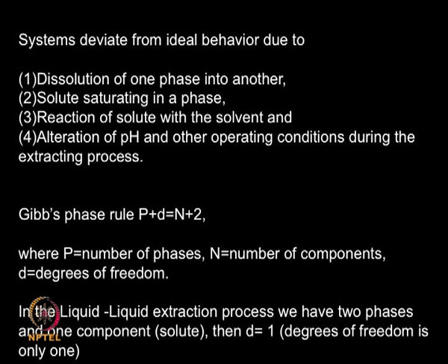So if the concentration of the solute in the solvent phase is known, then automatically the concentration in the fermentation broth or feed is fixed. So there is no extra degree of freedom, there is only 1 degree of freedom for this type of liquid extraction. So you see the thermodynamics plays a very important role in this process, and the phase rule determines the number of degrees of freedom present for this extraction process. Once you fix the concentration in the solvent phase, automatically the concentration in the feed phase is fixed, or if you know the partition coefficient, automatically both the concentrations are fixed. That means if you know the partition coefficient, the concentration of the solute leaving the stage in the solvent phase and in the raffinate are fixed, there are no more extra degrees of freedom after that. Okay.